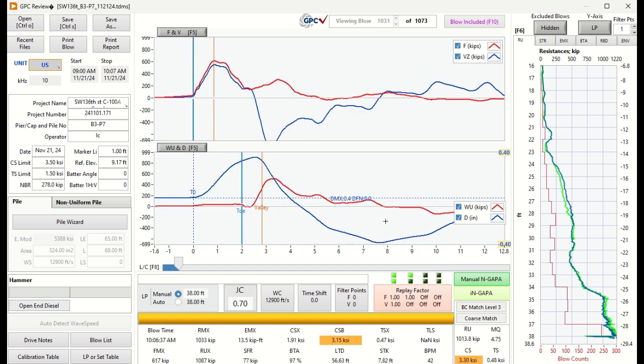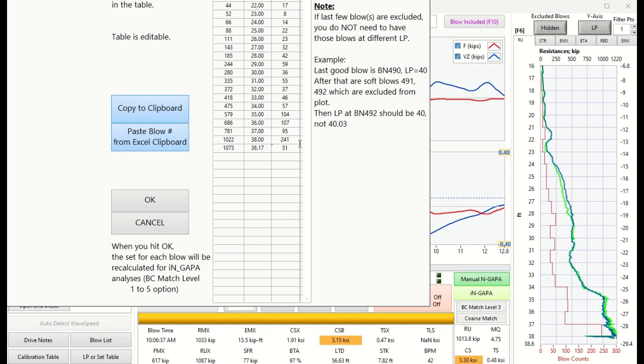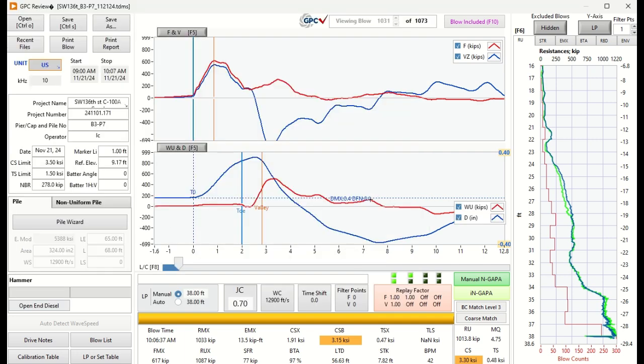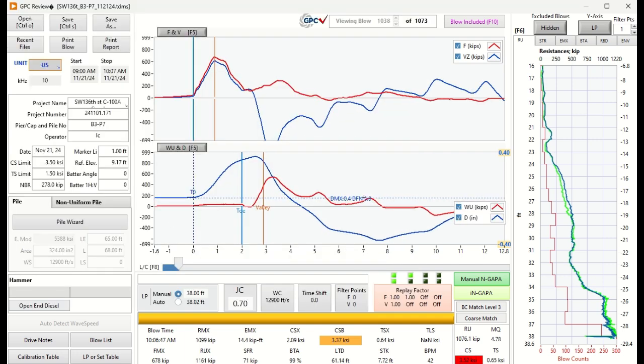So here, toward the end, it is almost 0 as well, because the blow count is very high. The blow count is 241 per foot. Of the last 2 inches, it is 51 blows for only 2 inches. So the inverse of these two numbers is approximately 0 as well. So that's the reason you have the DFN close to 0 here as well.